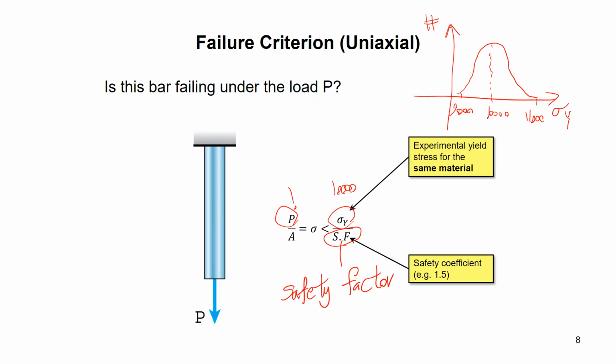Now, many manufacturers, not many, but a bunch of them do not exactly tell you the truth. They exaggerate their numbers to sell better. So they say 10,000, but maybe even if you take a ton of samples and test them, you see that no, really their average is 8, not 10. They are exaggerating it. So you cannot rely on an average in statistics, and you cannot rely on the word of a manufacturer, so this number is also not certain. And there are so many other uncertainties that will make you only use a portion of the total capacity, and you always use a safety factor.